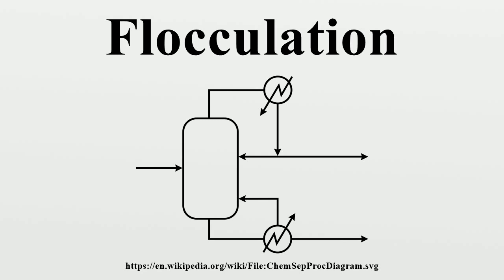Flocculation is a condition in which clays, polymers or other small charged particles become attached and form a fragile structure, or floc. In dispersed clay slurries, flocculation occurs after mechanical agitation ceases and the dispersed clay platelets spontaneously form flocs because of attractions between negative face charges and positive edge charges.